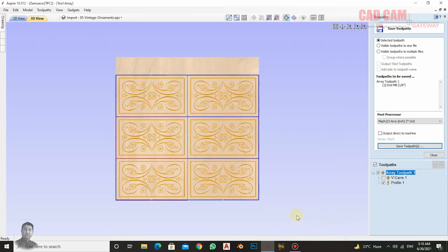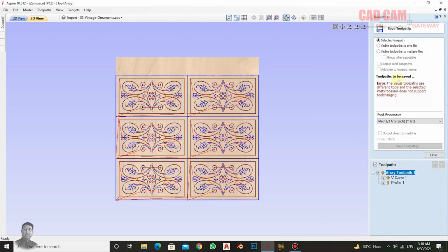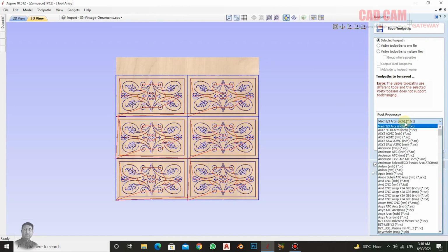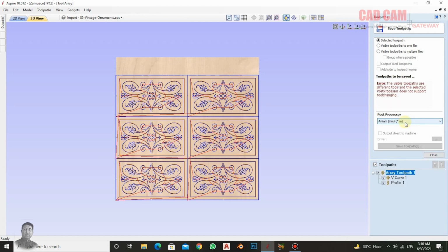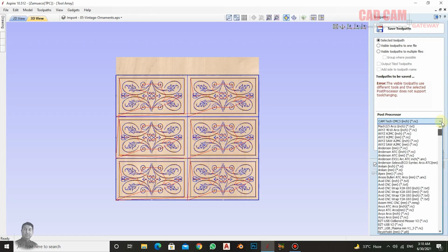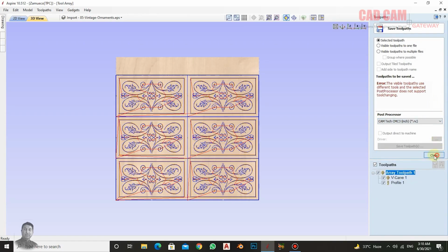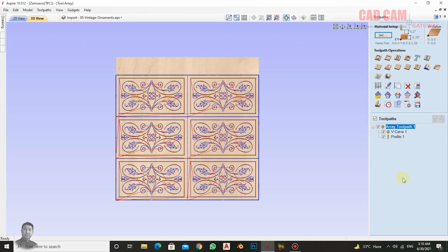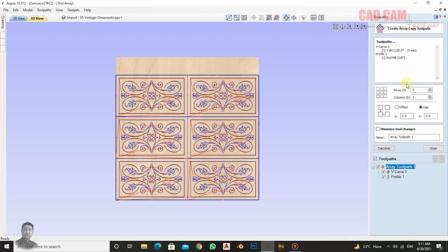And if you have an ATC machine where auto tool change is possible, then you don't need to do any of this. Just select your post processor, select all the tools together, and save it from here. Because this single head post processor handles multiple tools easily. We edited, applied toolpaths, and made changes. Double-click to adjust values, gaps, or other settings.